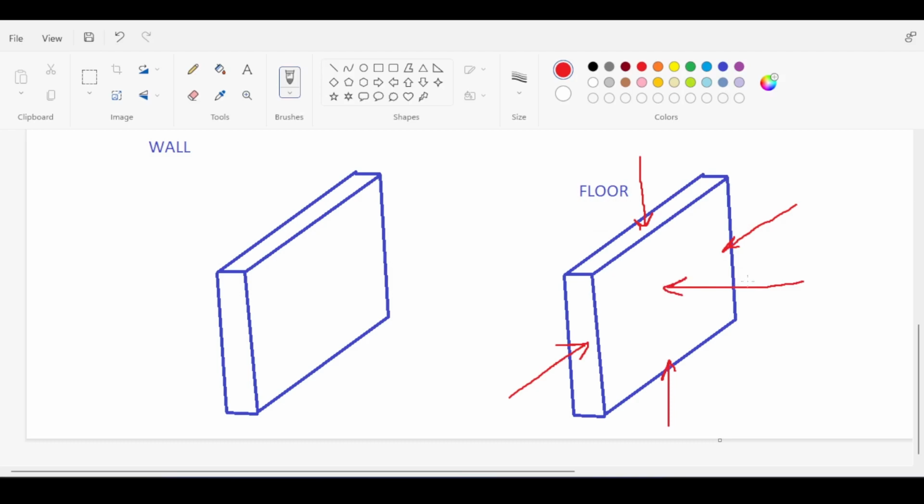It also feels the force in the z-axis perpendicular to that element. Of course, the z-axis here is the local z-axis. And this force will provide it with shear stresses that need to be checked against the concrete strength. It also feels the moment around XX, which is the bending moment in this direction, and the moment around YY, which is the bending moment here. And unfortunately, if you're using a shell element, it might struggle understanding the moment around the z-axis. It depends, of course, on the assumptions of the shell element, but sometimes it struggles. Now, this is what a floor element feels.